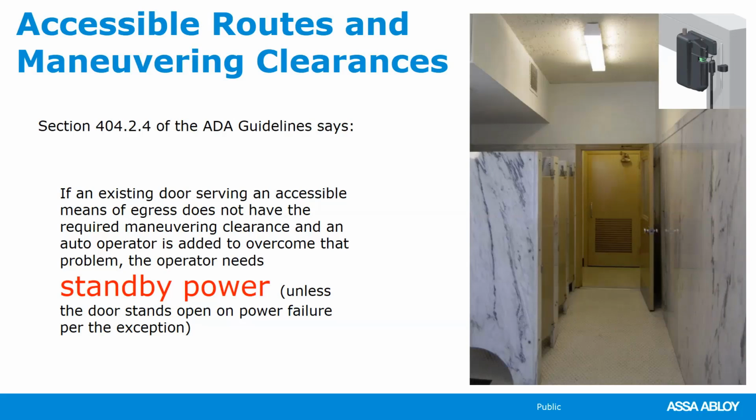Also, our specification writers come across this condition here. The picture shows an exit door. It has no side clearance and would require a wheelchair occupant to hold the door handle and reverse the chair to open the door. If you've ever tried this, this is not an easy task. So again, in order to exit with no side clearance, you'd have to grab a hold of the hardware and then back up or reverse.